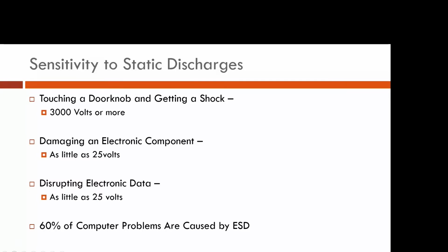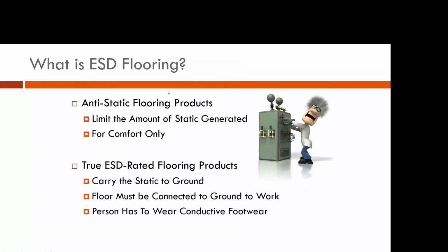So one way we prevent this is with ESD flooring. ESD flooring is designed to remove the charge off the human body. Very different than the ESD function on top of a bench top or a tabletop. That system is designed to remove charges off of components and small pieces.